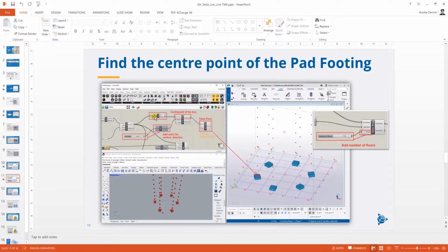Okay, this is the area, and then get the area from the geometry, and then the centroid, we need to link that one to the linear array. Okay, so it's a plenty of commands that we need to add here. So let's do that one by one. First is we need to add the area and then the linear array. Okay, area and linear array.